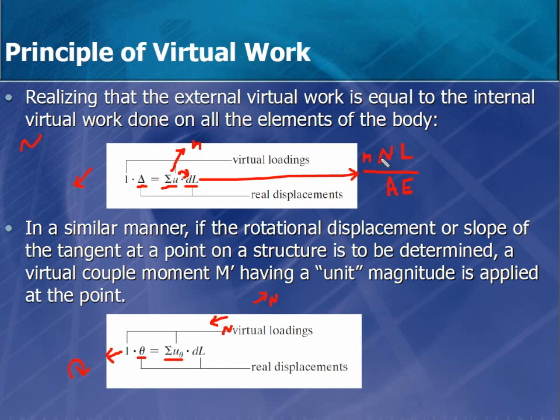Now if you remember, in the previous one it was N square. The N square was there. Why? Because the deflection was directly under the load, so we didn't need this virtual load. And at that time we used P here. If you remember, it was P delta. By the way, the 1 over 2 from that side and 1 over 2 from that side are going to cancel each other.